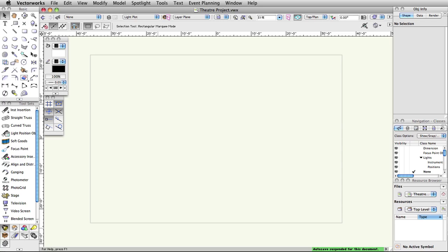We will now create a couple of lines to represent the center line and plaster line, as well as place a locus point which will be used as a reference for the start of the theater walls. Then we will turn these objects into guides. In the view bar, set the active layer to Theater Architecture.